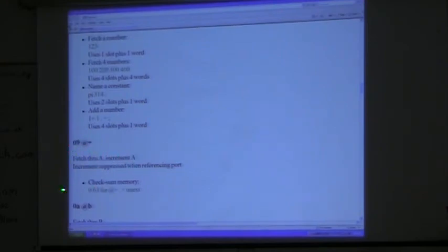Fetch plus fetches using the address in the A register and increments the A register. This is how you can checksum some memory. Put a 0 in the stack, and for 63 times, do a fetch plus and an add and a micronext. You might also mention that the RAM address wraps from the top of RAM back to the bottom of RAM, so that if you use one of these incrementing pointers in RAM, you're going to stay in RAM. Good point. Or if you're in ROM and you're checksumming ROM, it would wrap around there too.